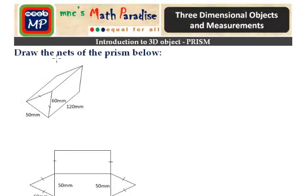Let us draw the net of this triangular prism. So here in this triangular prism, this is one triangular face, and there is another triangular face at the back. For a 3D object, we can't see everything. In this triangular face, this edge is 50 millimeter, and these two edges are equal, and each of them is 60 millimeter. So to draw this net, let's start with this triangular face.